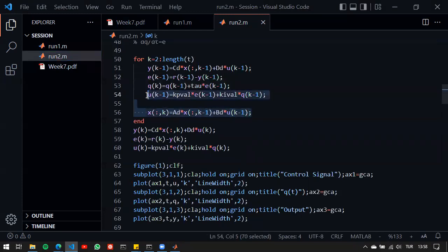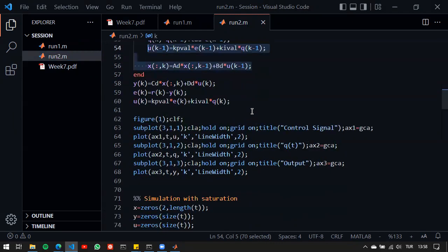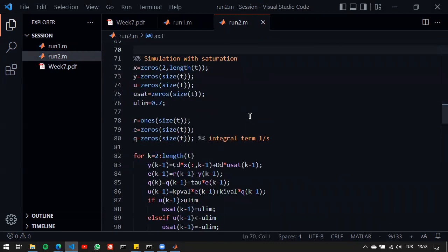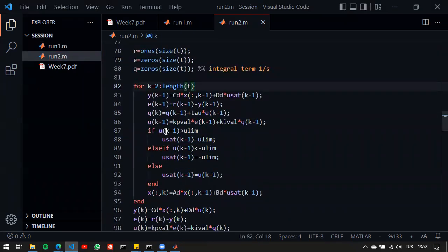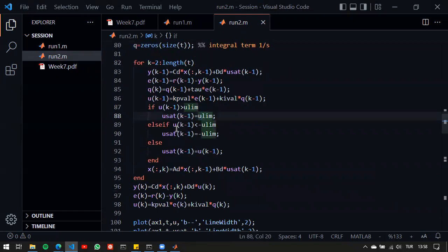But here we don't have the hardware in the loop. We have just a simulation in the loop. So that's also important. And we've seen that using this approach for simulation or Simulink, it is possible to reach the internals of this closed loop, and we can then manipulate the control signal. By the way, I've shown you the saturation element, which is a nonlinear element. So our overall closed loop is not linear anymore.